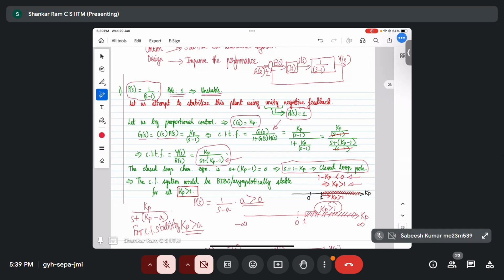Okay. So that means, sir, my next level question is that if KP value is like 1 or like 1 lakh, what is the implication on actuator or any system design in that sense? So that will come later. See, I think Roshan, you built a hypothetical example and I answered that. Point number 1, because you and I don't know what will be the value of A. I built a hypothetical example, A to be 1. You built a hypothetical example, A to be 1 lakh. So you and I have now learned that if KP is greater than A, we have closed loop stability.